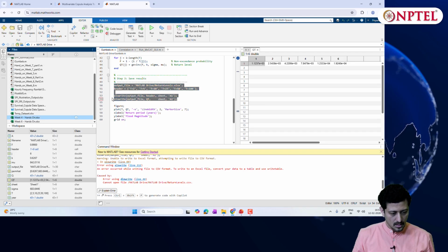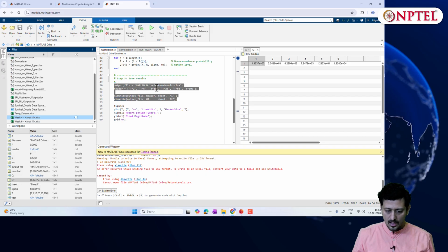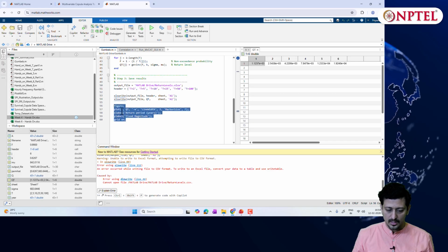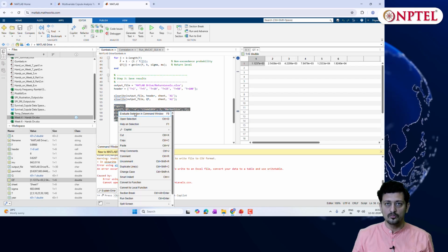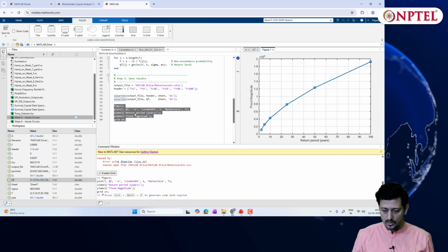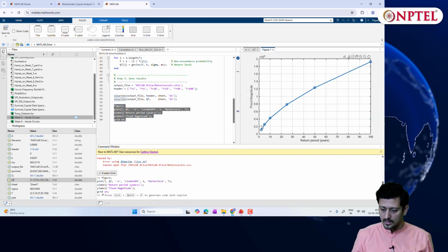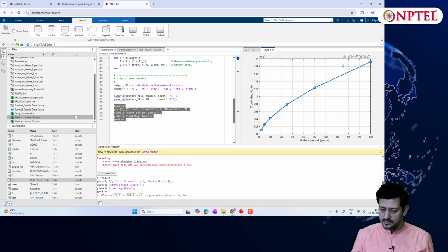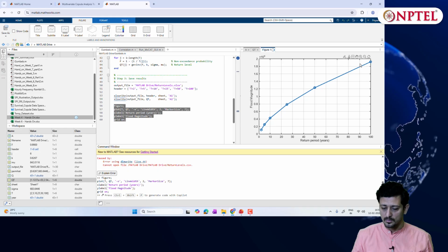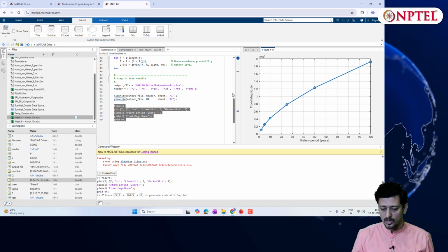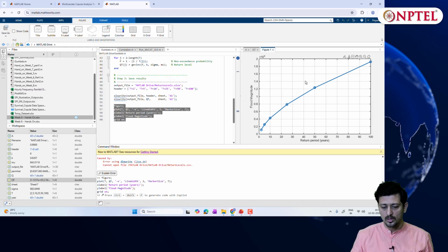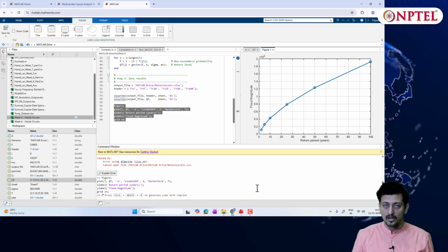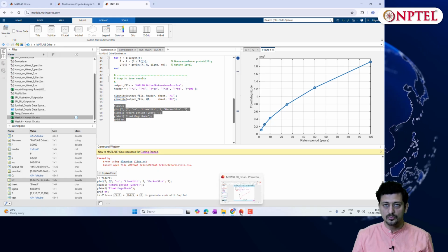This particular output can be saved, and finally you can plot this figure to visualize how the flood frequency curve would look like. So you can see your FFA curve. It is of this characteristic where for close to a 100 year return period, the discharge is very near to 20,000 meter cube per second. For any return level, you can simply interpolate in between, and if you require, you can have it for higher return periods as well. This FFA curve is very useful in hydrologic analysis and design. So let us continue further.